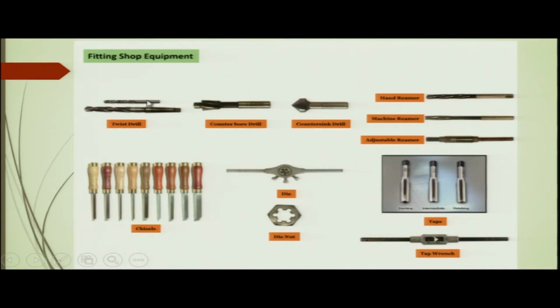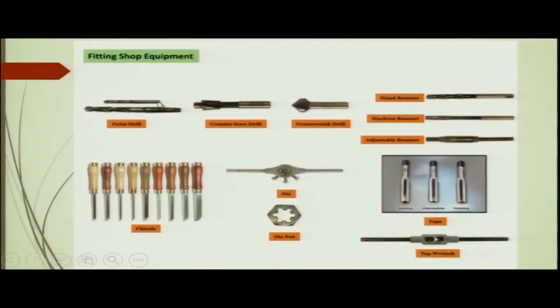This is the portion where the drill will be used, and as you know the drill is used to make a hole in a metal surface normally. This drill has to be mounted on a chuck or a drill holder. This is the shank, which is used to mount the drill in the drill holder or the drill chuck, all right.